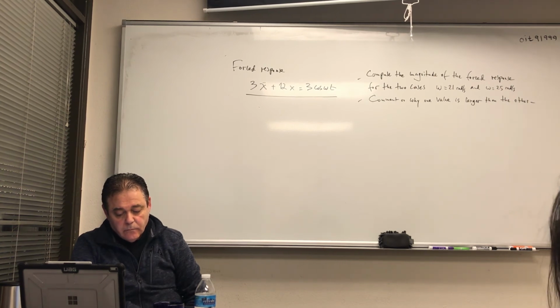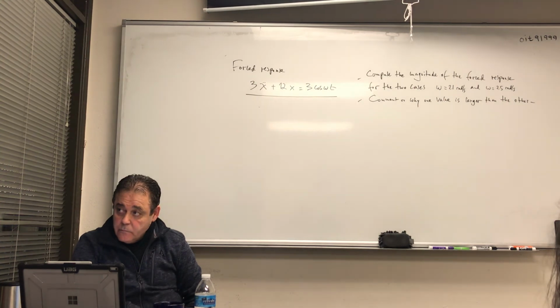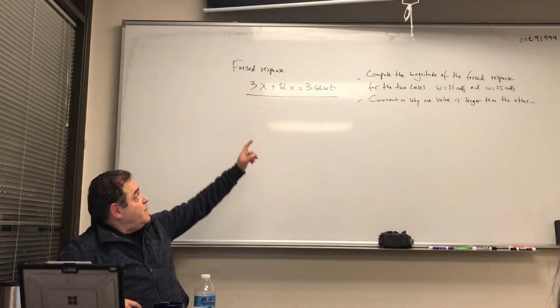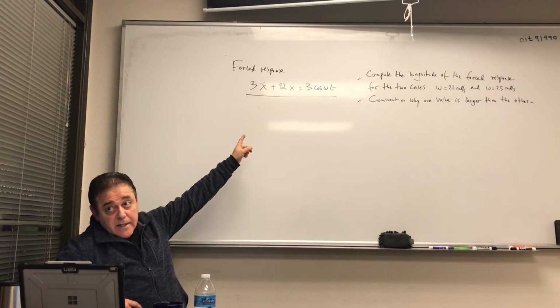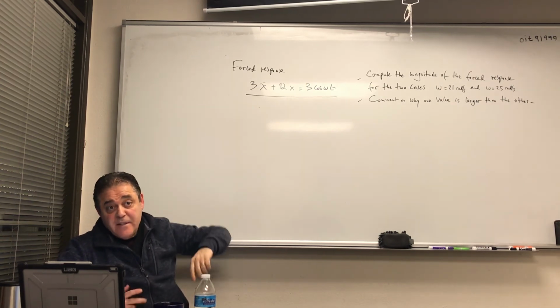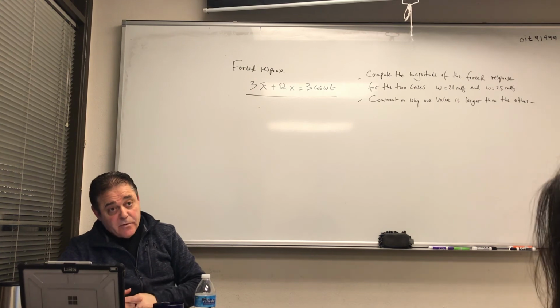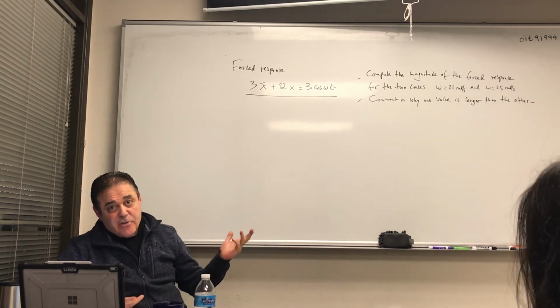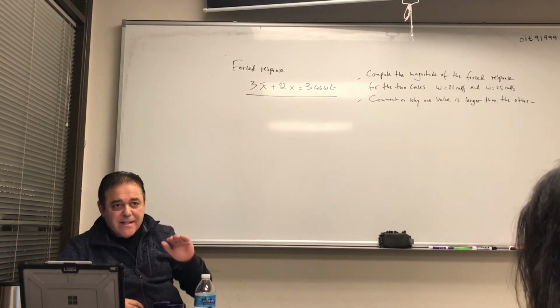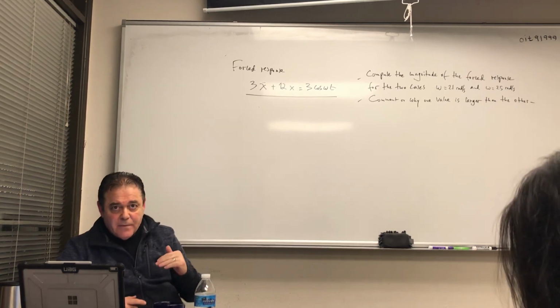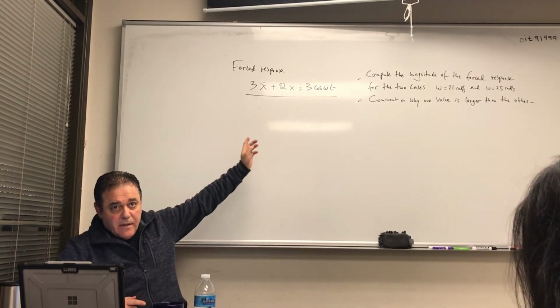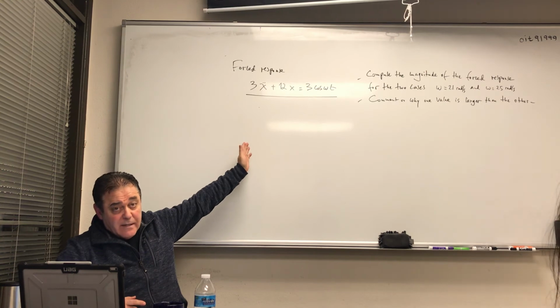So you just look at this and say, okay, this is undamped forced vibration, and go and look in that section in the book to find out. You probably notice from there that it is undamped, so the problem does not need to tell you that it is undamped, because you don't have an x dot. There is no c, okay? Those are the subtleties of these types of problems. Somebody gives you that, you should determine from looking at that there is no damping.